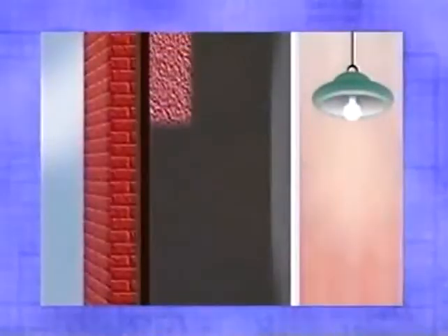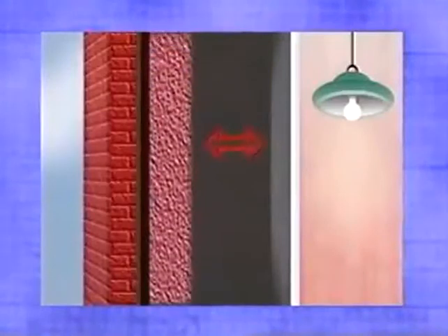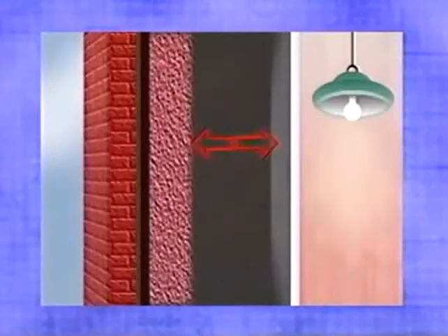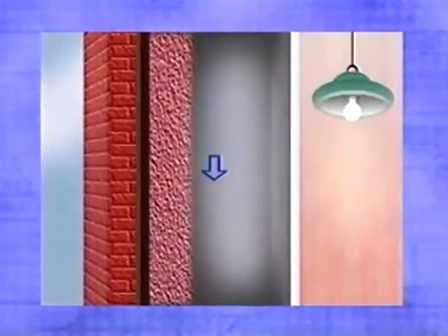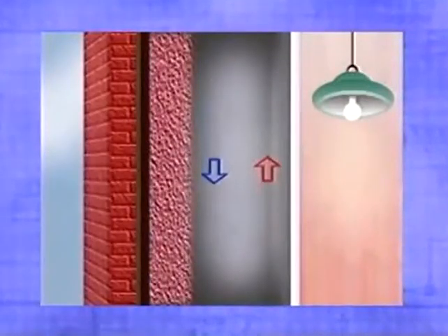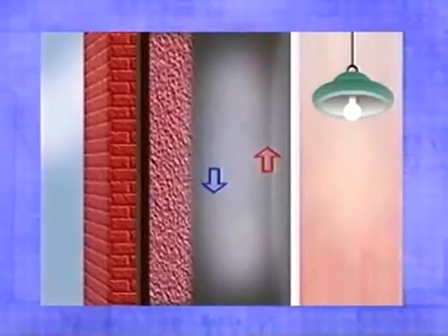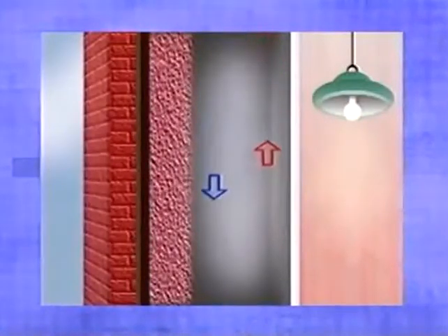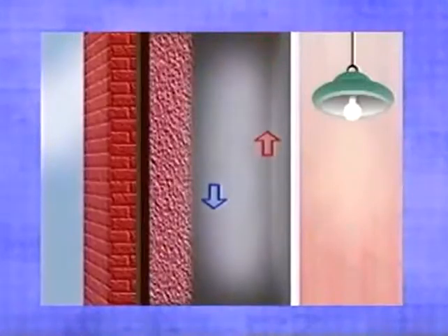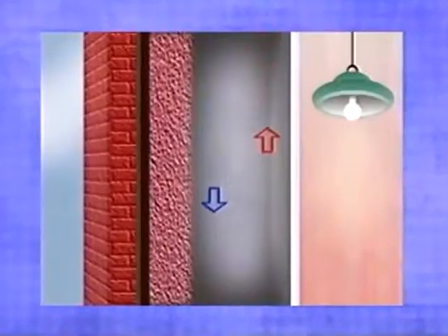Misalignment occurs when there is distance between the insulation and the air barrier or sheet good, such as drywall. This gap allows air to circulate inside the cavity. This is called a convective loop and can cause big comfort problems. Typically, everybody understands that warm air rises. That's a pretty fundamental thing. What people don't understand is that even in an enclosed cavity, you can have warm air rising.